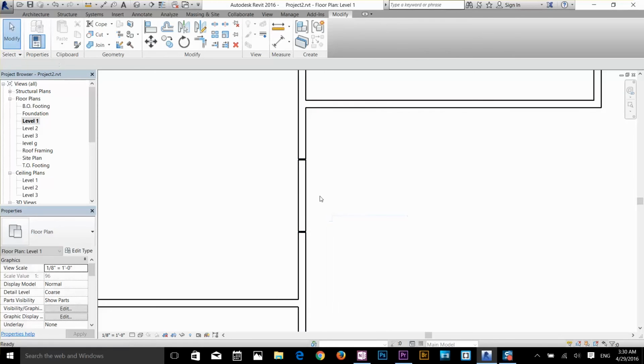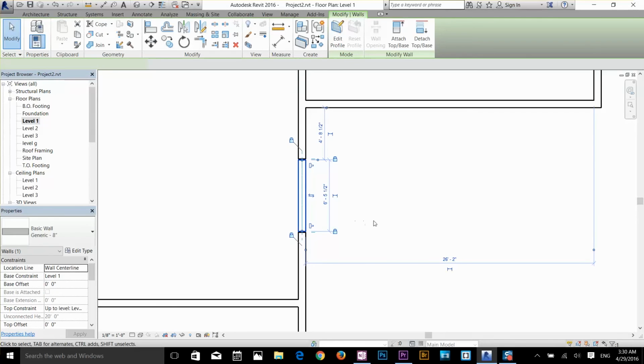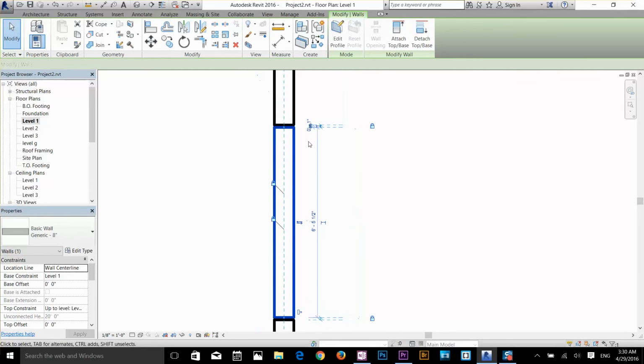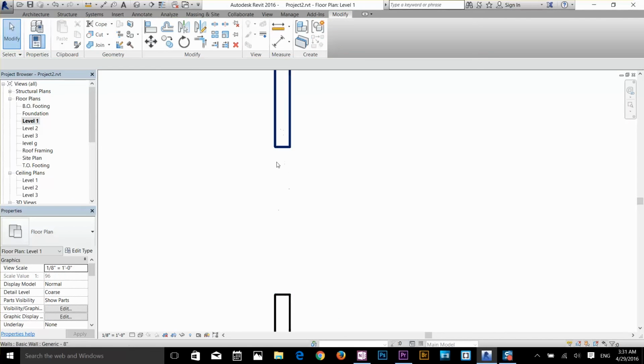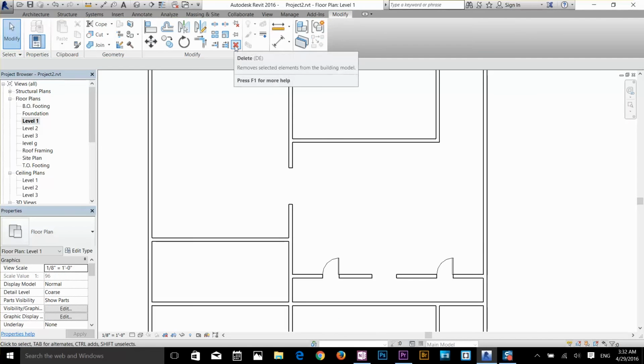So you can click on the modify command, and now it's a proper separate object, and you've got a lot of controls here. You can just flip that. It's a wall, that's why I can't show you. Alright, so you can delete that and you've got the gap there. Well, that's the delete command. Click on it, click on an object, press enter, and that will be gone.